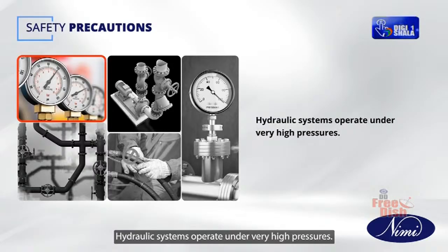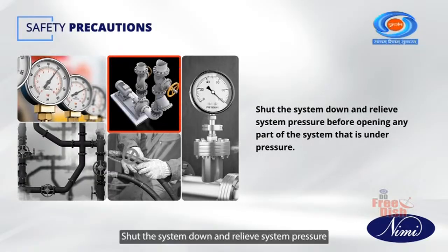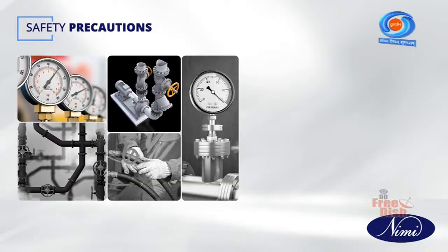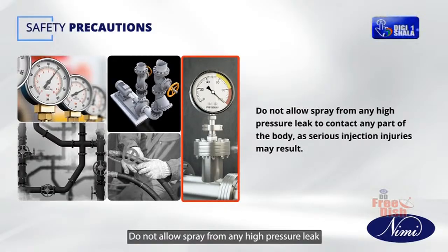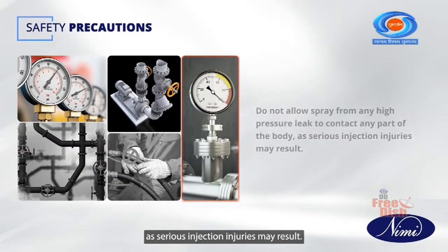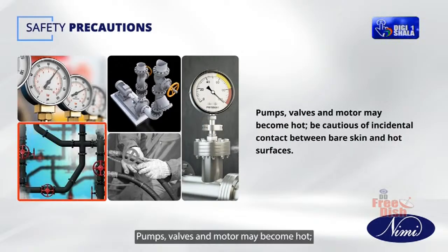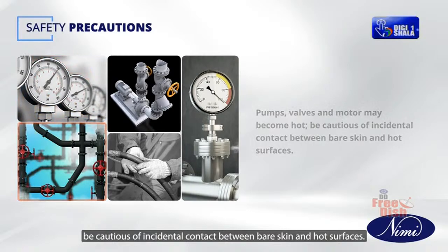Hydraulic systems operate under very high pressures. Shut the system down and relieve system pressure before opening any part of the system that is under pressure. Do not allow spray from any high pressure leak to contact any part of the body, as serious injection injuries may result. Pumps, valves, and motors may become hot. Be cautious of incidental contact between bare skin and hot surfaces.